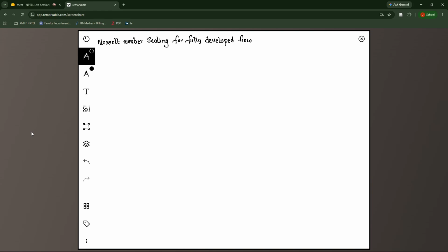We can use the boundary layer theory that we already developed, and from that we can write the Nusselt number will scale as Reynolds number to the power half. And interestingly, here Prandtl number also to the power half. And then we have an extra parameter, x over d, which is basically the entrance effects. As x value becomes larger and larger compared to the diameter, then eventually there will be a point where the effect of this particular term is negligible, and then it will only depend on these two quantities. So this is in the developing region.